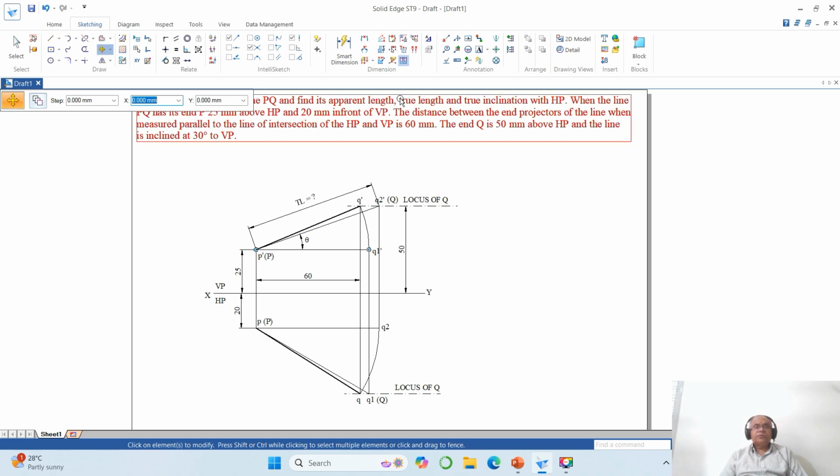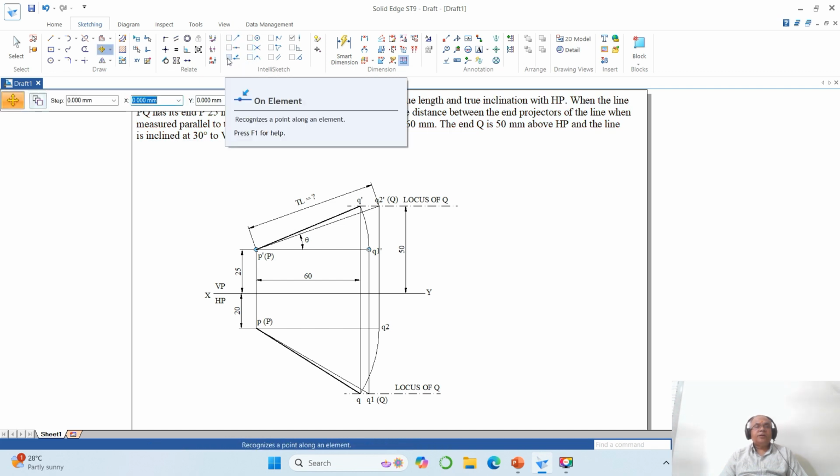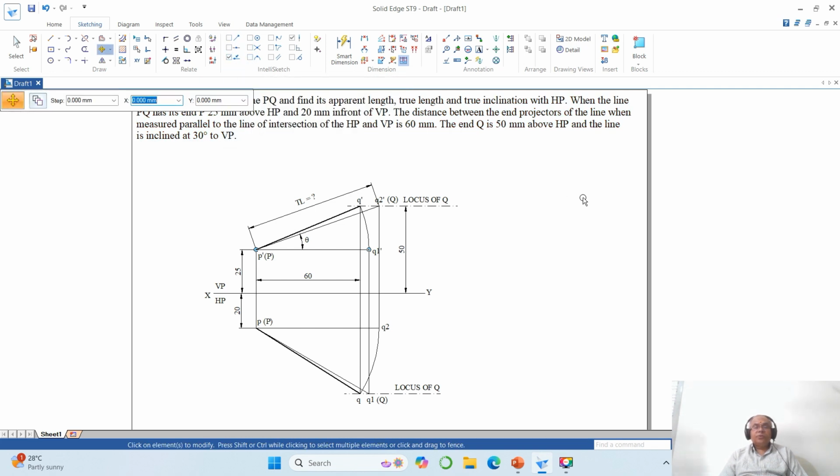Okay. So then I want to show the directions of projections. To do that, remove endpoint, intersection and enable point on element. So here the first thing is you project this point, that is you take this line. From here you take this, and again from here you take this, one point is over. Now we have the true length line, this is okay.